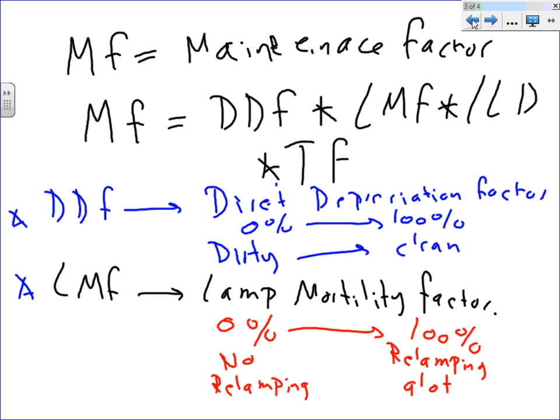When you design the system, if you did the calculation based on 80-foot candle, and you physically measure it day one when you power it, you might end up with 100-foot candle, very bright day one. Why? Because of all these derating factors you added. But over 6 months, a year, you're going to average 80-foot candles.